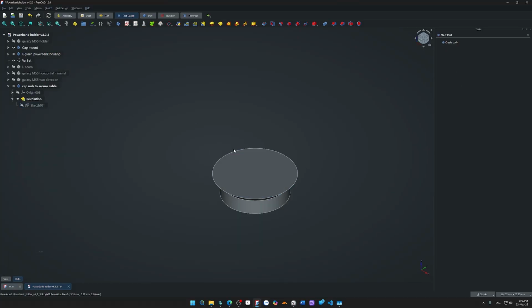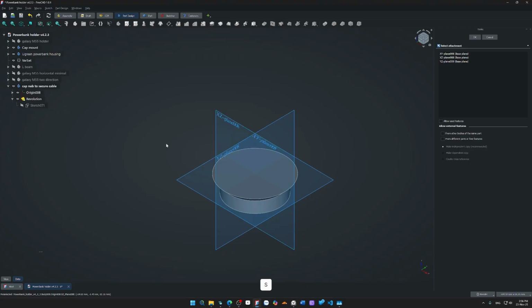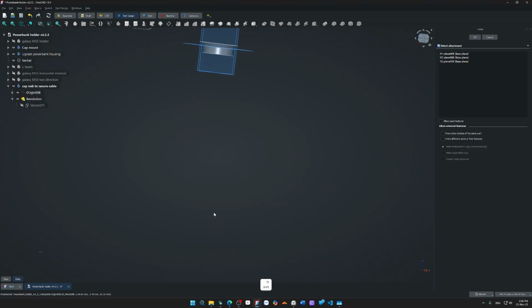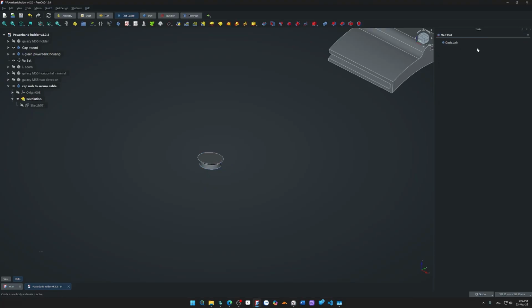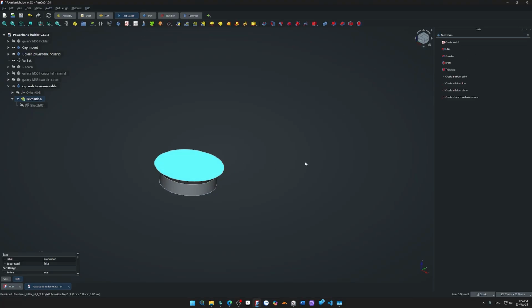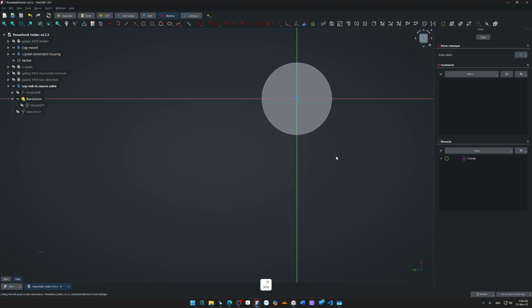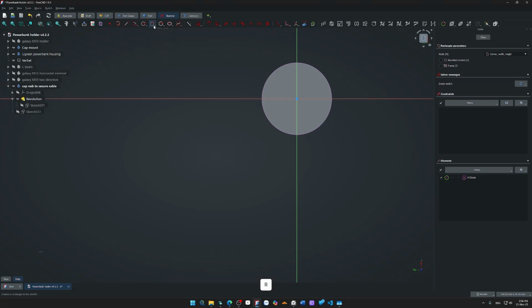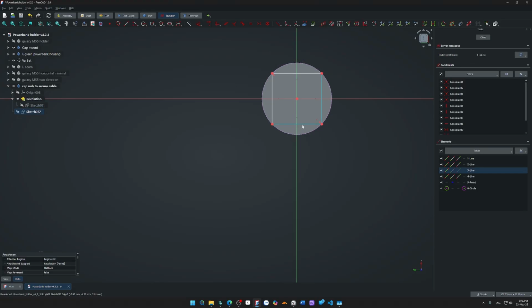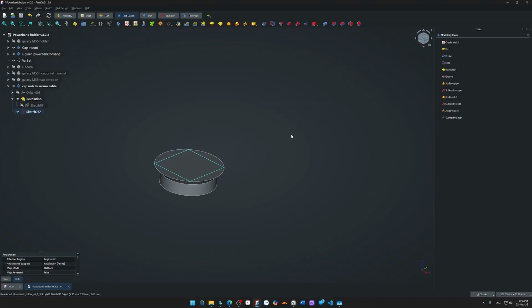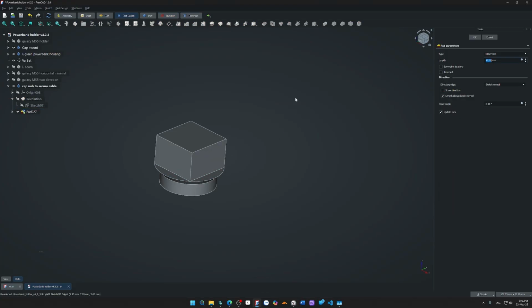Because right now I'm going to make a sketch. Okay, it is doing the same, right? So using this surface for a sketch, reference. I want to create a square. Make the two sides equal. And now I got that. Gonna extrude it by, let's say, 10 millimeter.